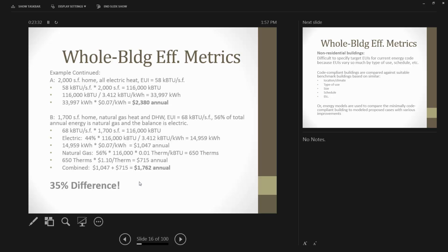That same house, if we're going to go in and replace all the windows in the house, and it's going to cost $10,000, it might save us 30,000 BTUs, and run the numbers and annualize that out, it may save us $500 a year, but now that's going to take us 20 years to pay back. Don't worry about those numbers currently. It's what we're trying to drive to when we start getting into the actual design and the weatherization of the buildings. One of the biggest things about energy efficiency and conservation is that it also has to be cost effective.